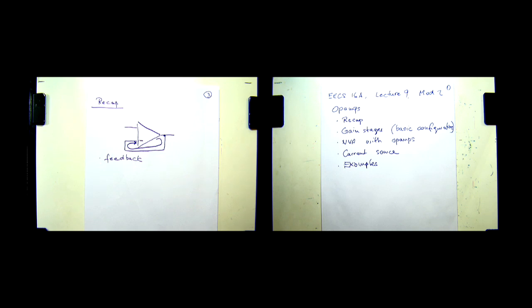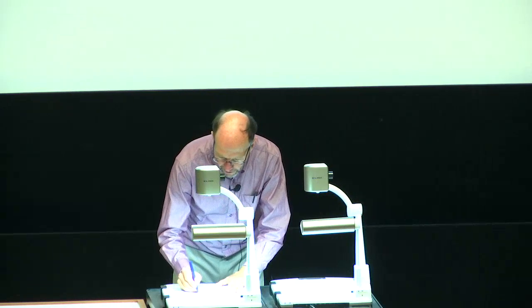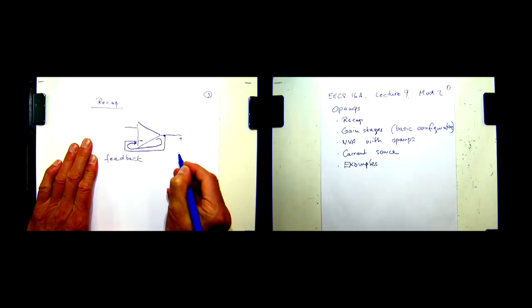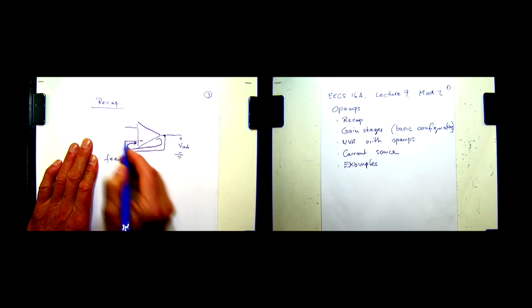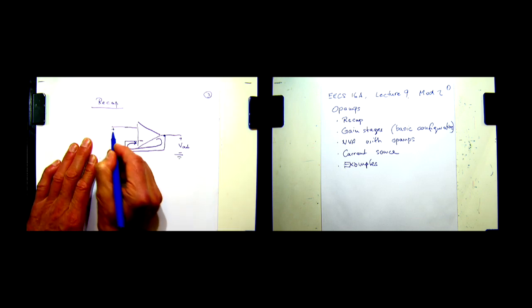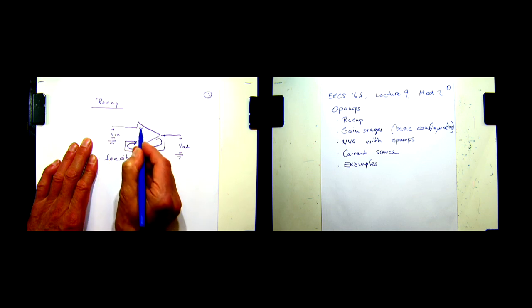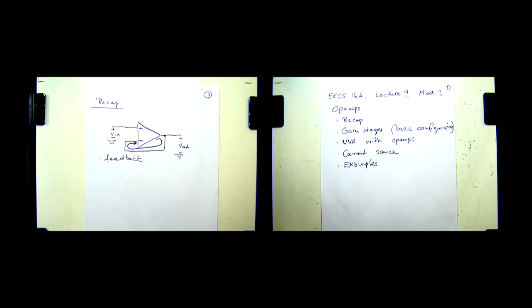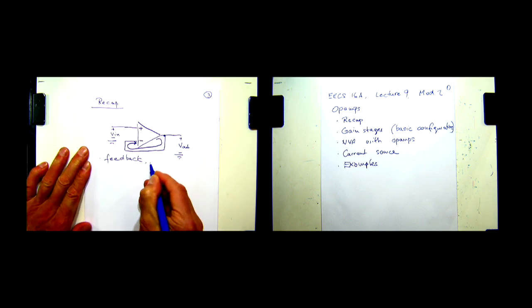And if we have such a feedback loop, we want this feedback loop to include the minus sign. Okay? And then of course we have an output here. And over here we have an input, and that one needs to go to the other terminal of the operation amplifier. So, negative feedback.